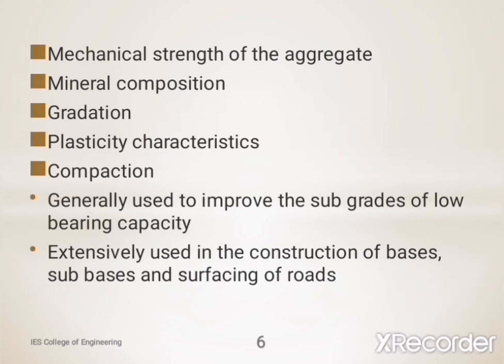Minerals should be weather resistant, and certain materials such as sodium sulfate and sodium carbonates cause large volume changes due to hydration and dehydration. These are detrimental to the stability.